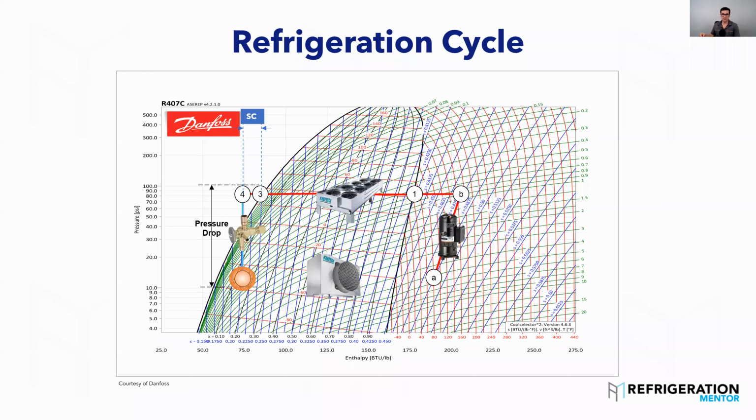So you do the pressure drop here, the metering device. It could be a cap tube, it could be a TX valve, could be an electronic expansion valve. We're seeing so many electronic expansion valves out there, and if you're in the VRF or VRV world, it's all electronic valves. So you're going to see more and more of that. We get back into the saturated curve, your thumbprint. You're back into your SST. Then that evaporator starts to absorb the heat from the product, from the people, from the room, and then we hit our dew point again, and then bam, that's your superheat right here.